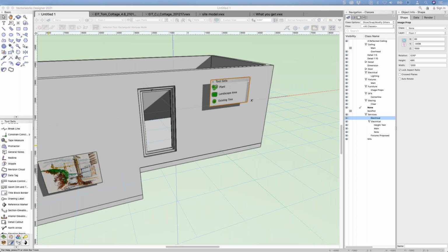Grouping the extract surfaces across layers is new to me. Yep, so Andrew, you have to turn on show snap modify others to do that. And if they don't line up perfectly, Vectorworks will know, so be careful of that one. Yeah, great for board and batten, but not for a sentiment.